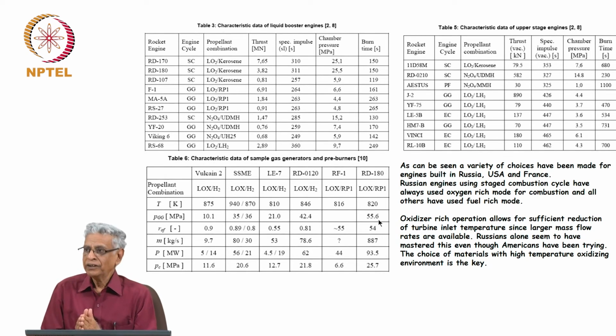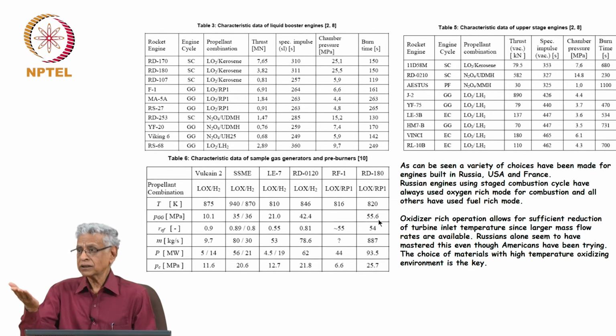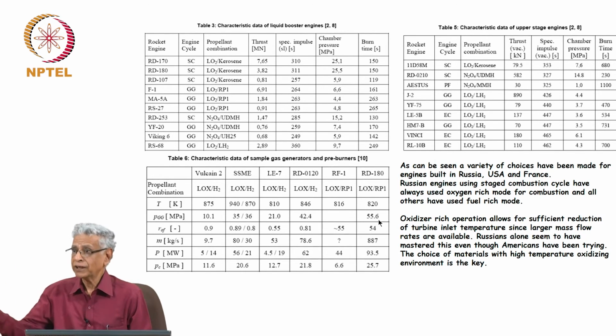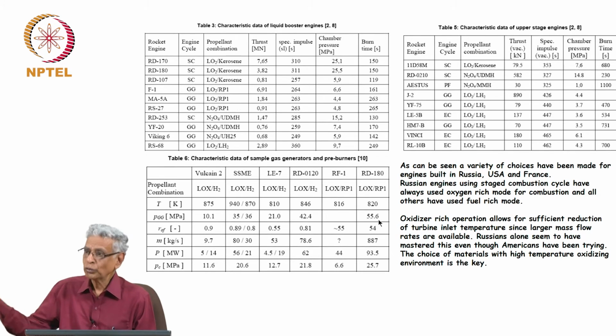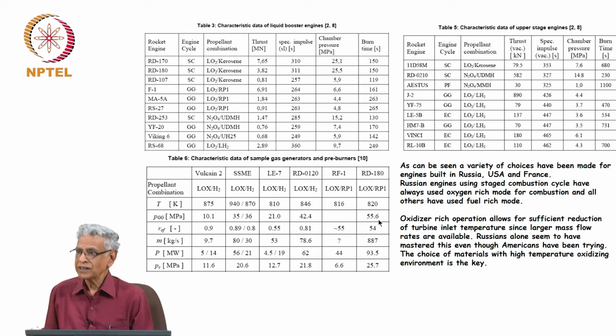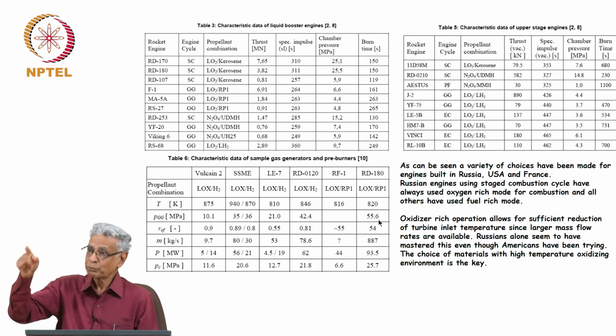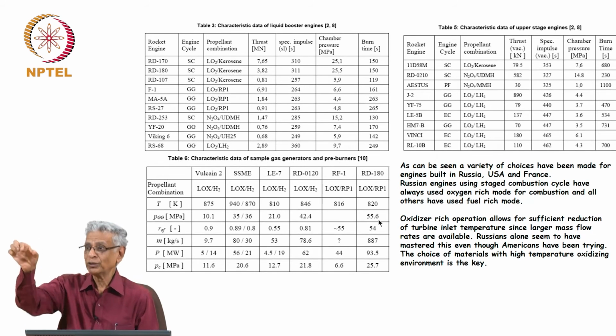But the basic question is, if you are using oxidizer rich operation, using that as a coolant, and in the case of LOX hydrogen, you can use hydrogen as a coolant also, because ultimately you are going to deliver it in the form of a gas, no? Even in the case of the design which is used in ISRO, your hydrogen is coming as a gas to the coolant channels, and the pre-burner creates products which are oxidizer rich and pushes into the core.